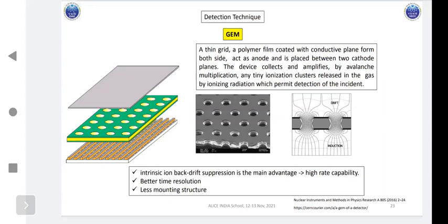If it is low, and you have some background excitations, they can initiate ionization, but you don't want that. When a charged particle comes, you want that charged particle of particular energy to hit the molecule substantially and give the ionization, not a background effect. So if your ionization potential is very low, it is a little risky to use. This is one thing. Another thing is inertness.